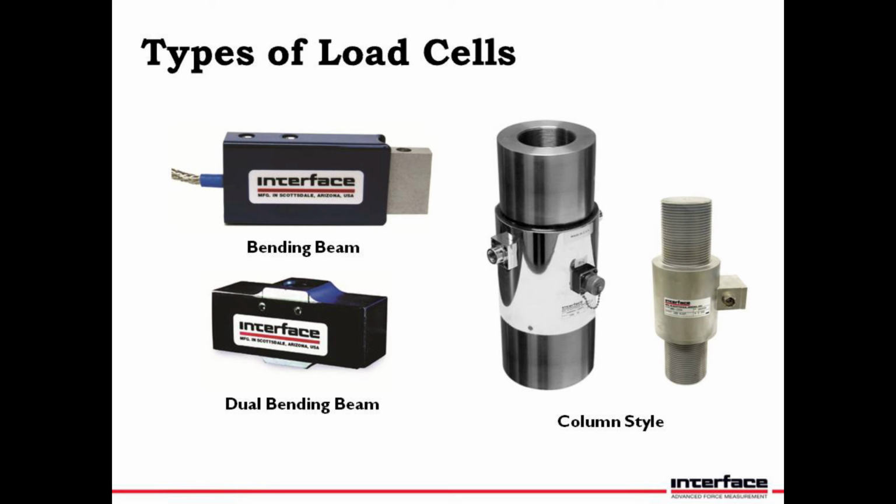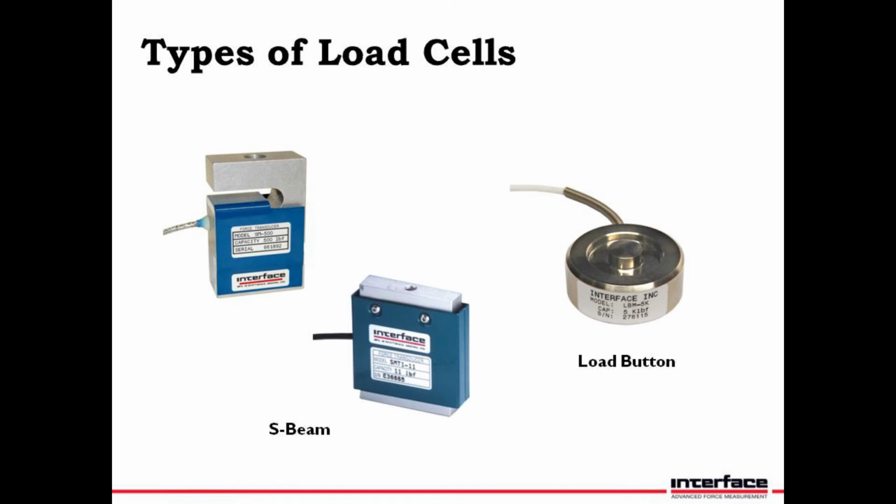And then on the right there is a column style load cell. Column style load cells are popular, most popular within test stands in my experience. They're convenient in that they offer a high rated capacity with a smaller diameter where a low profile may not fit.